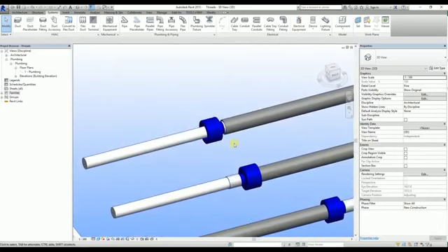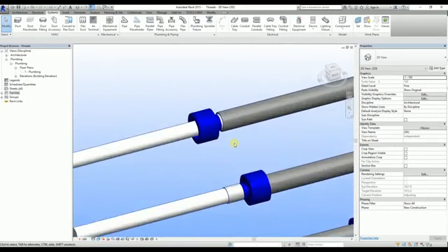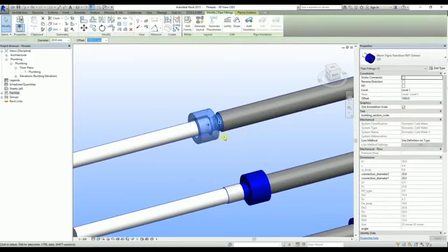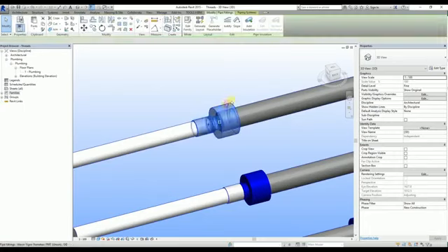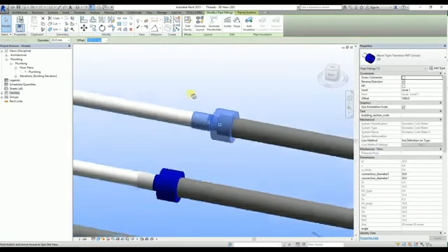Depending on the pipe with which we started to draw, we might see that the fitting is not inserted properly. In such cases, we need to select the fitting and use the reverse direction checkbox to fix its orientation. If you don't notice and fix such issues for some reason, don't worry, because the working lengths stay the same.